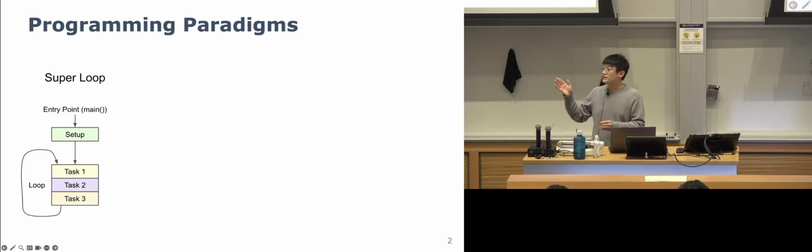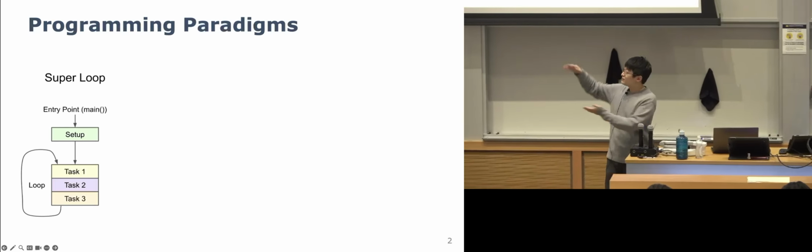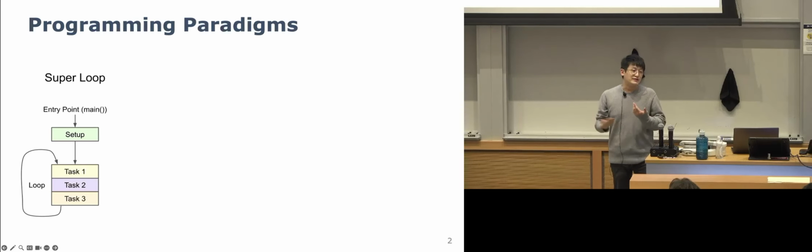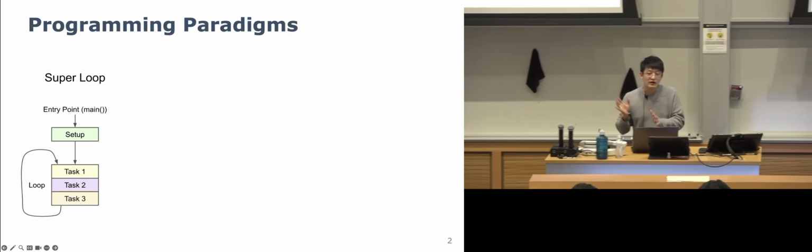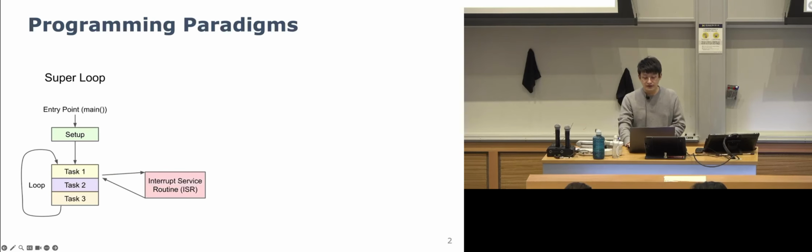But then we talk about some of the limitations of this. For example, if this list got humongous, there are going to be a bunch of delays on certain input signals, or on certain output signals that are supposed to come out at more critical times. To deal with that, we introduced interrupts, basically a bunch of ISRs, to help with the responsiveness.